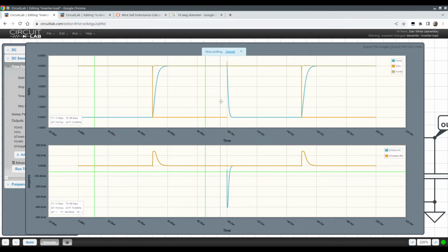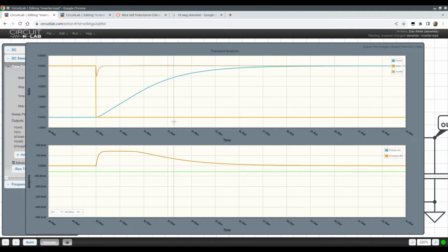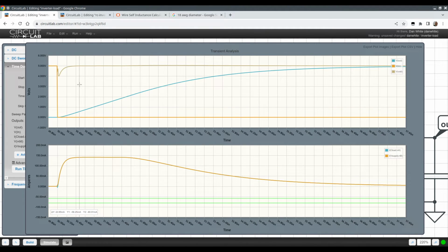Thinking about this for a second. And what do we have? Let's zoom in on our rising edge, because if you remember, the rising edge is where the action is for our voltage. All right, input goes high to low, output rises up. Our VDD, though, at this moment, VDD drops by about 1 volt.